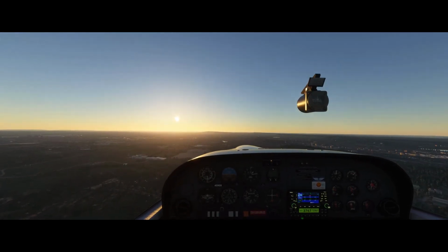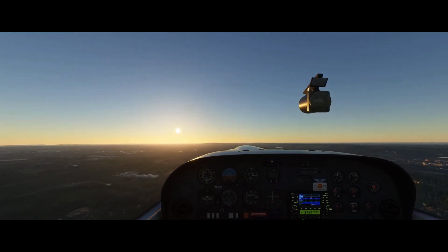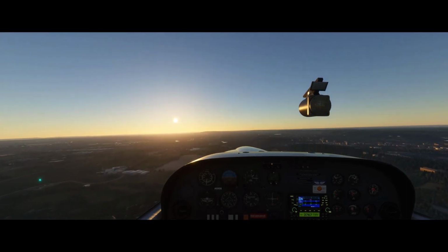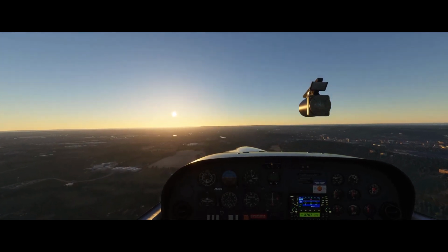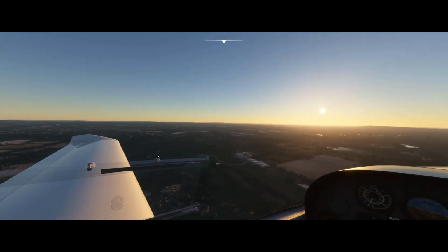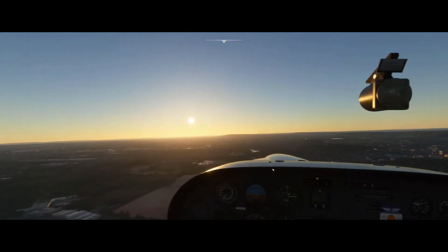Don't worry too much about the height, guys, in terms of keeping it. You're in a simulator. You're doing this for enjoyment, but you can see the runway there that we're going to land on. And what we'll do is we'll just trim slightly. We'll pull the power back so we've got less of a rate of climb. We normally call downwind around about here, so when we're parallel to the numbers here, you can see that we're nicely going along here.